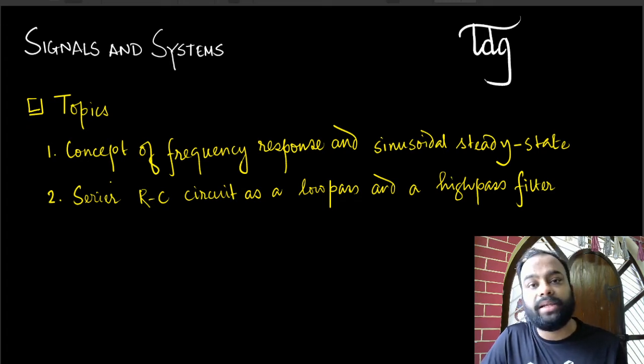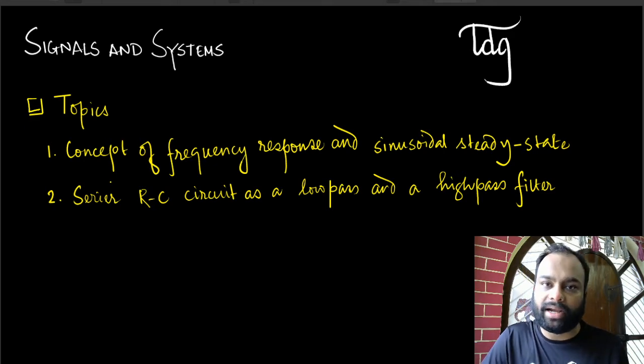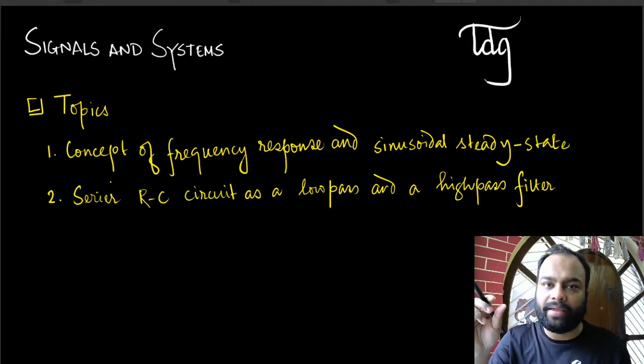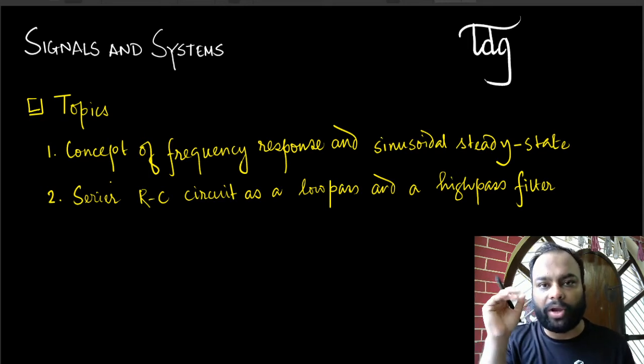So linear time invariant systems, right? If theoretically all the elements are ideal, so I have ideal resistors, ideal capacitors, ideal inductors, they are all perfectly linear and time invariant elements. So the entire electrical circuit that we get is linear and time invariant. And the property that we state while teaching circuit theory or basic electrical engineering is that if I excite an electrical circuit with an AC supply, which is represented through a sinusoid, then all the outputs, namely responses of elements like currents going through elements and voltages that appear across elements in the steady state, are also going to be sinusoids.